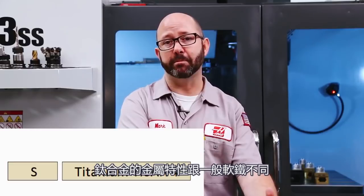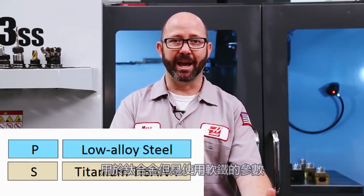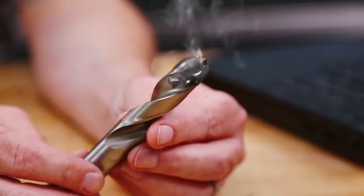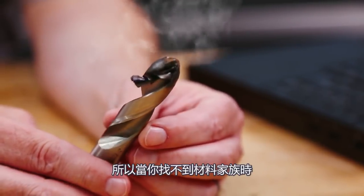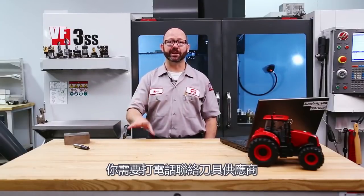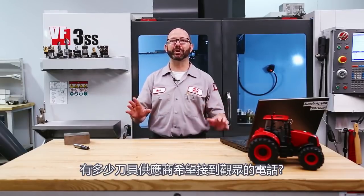Titanium has a different machinability than mild steel. If you try running a drill or an end mill in titanium at cutting speeds meant for mild steel, you are going to melt that tool. It will overheat and fail. So, if you can't find what material group your stock should be in, then give your tooling representative a call. They would love to hear from you. How many tooling reps out there would love to hear from one of our viewers and talk tools? Yeah, that's what I thought.